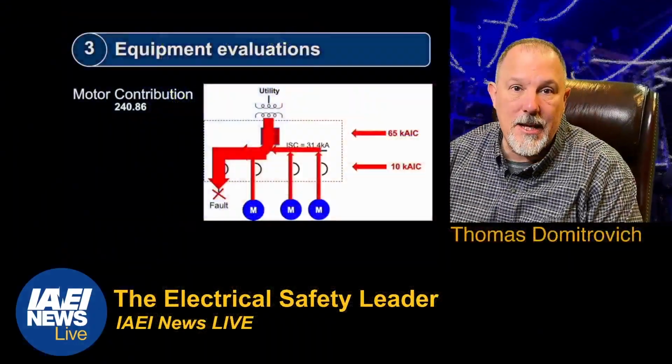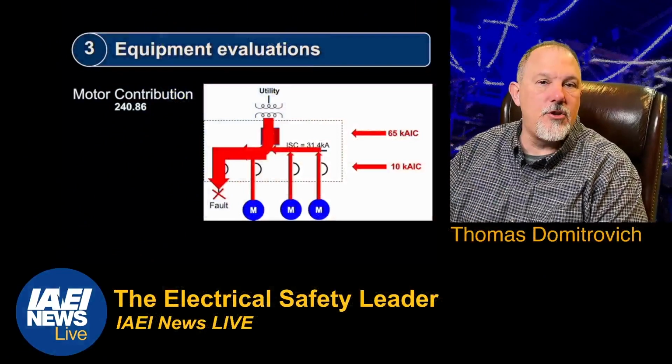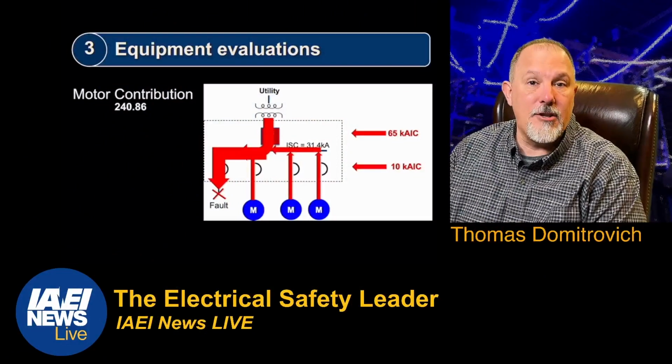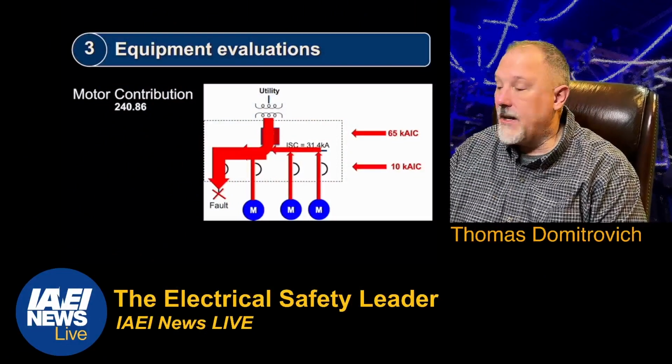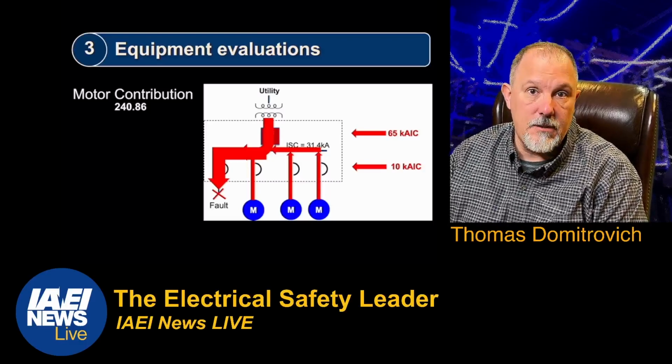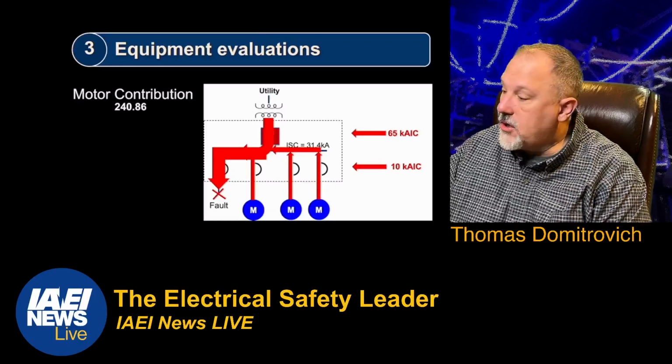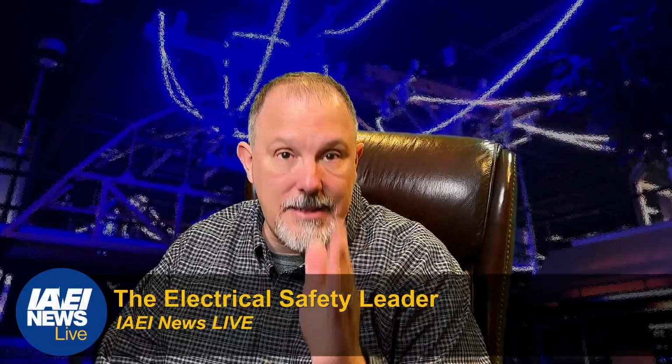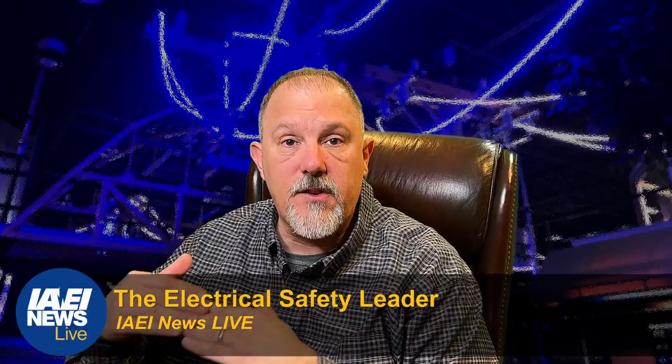And in some cases, if you're doing a series rated application and you didn't consider motor contribution, you're not only violating the National Electrical Code, but you could have an unintended rapid disassembly in the field because of misapplication. So it's very important to understand the details, the devil's in the details, when we make these decisions to reduce the cost of the electrical infrastructure. What else? So we got all of these different costs.